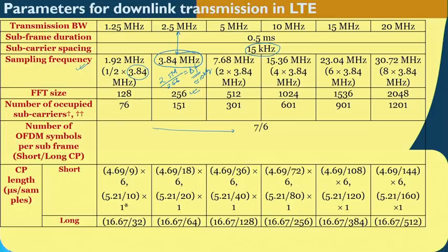Effectively there is a wider bandwidth. So, if this is 2.5 megahertz, we have let us say 3.84 megahertz, which is wider bandwidth, and then you divide this by 256, you are going to get 15 kilohertz. Okay. And now, one would argue that 15 kilohertz subcarrier spacing, if I multiply by 256 subcarriers, then one is going to fill out an entire set of frequencies.